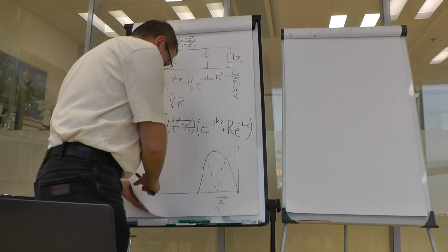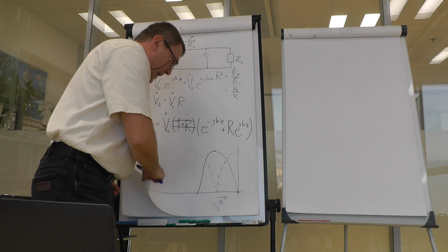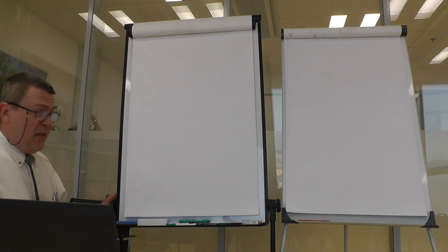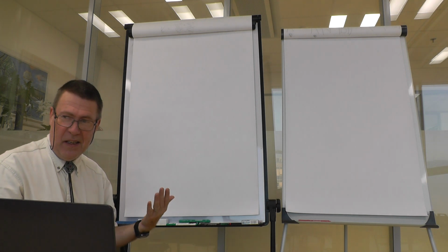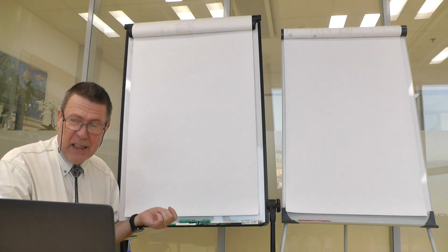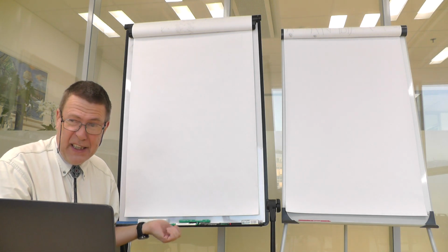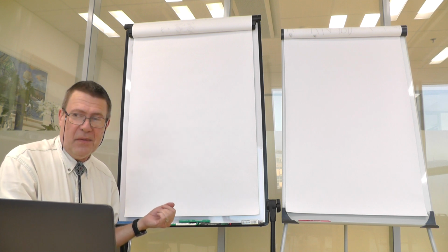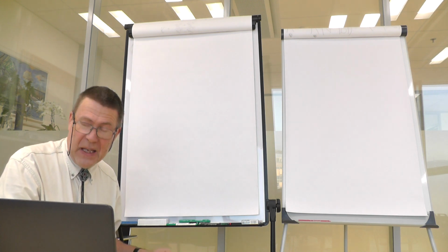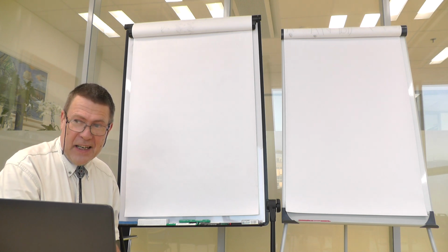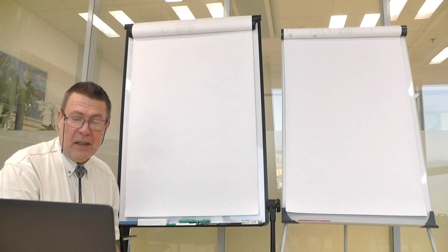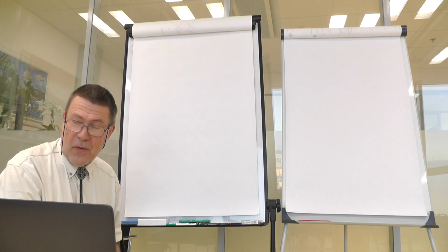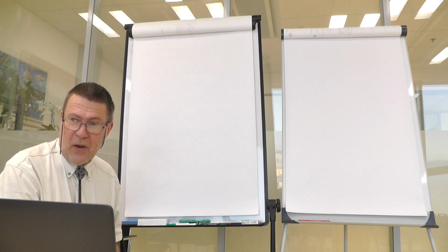Now, in fact, there are at least two ways you can destroy a coaxial cable by the power that you submit through it to the load. The first destruction would be high level of current in the conductors that would cause heat and melting of the conductors. But technically this is not at high frequencies very much the case. So we have the other way of destruction, and that is by exceeding the maximum electric strength within the dielectrics of the coaxial cable.